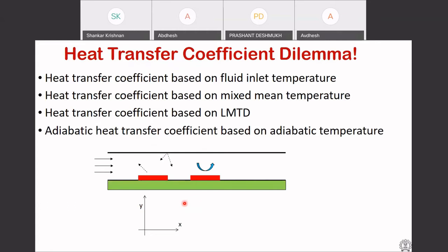If I say the Nusselt number for flow through a pipe which has a constant heat flux, then I would say it's 4.364. And whether the pipe diameter is 6 mm or 10 mm or 100 mm, I should get the same Nusselt number. So the question is, can I get an invariant descriptor of the heat transfer coefficient in such a complex system?